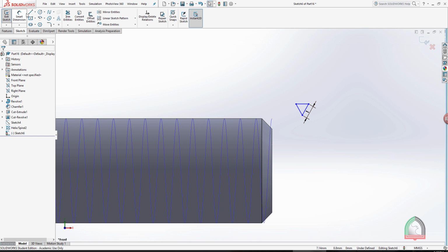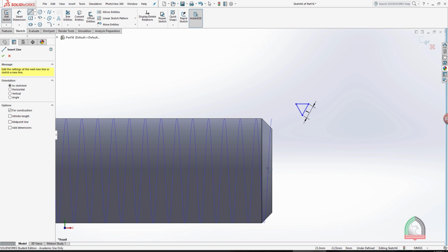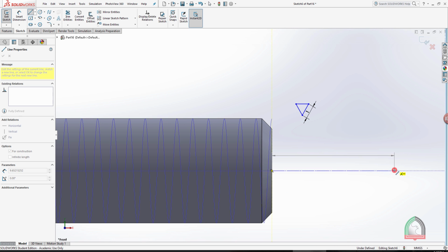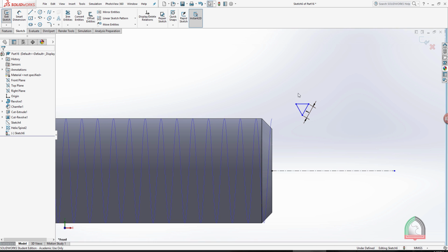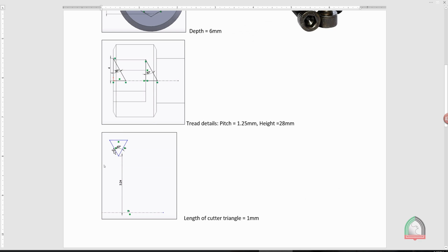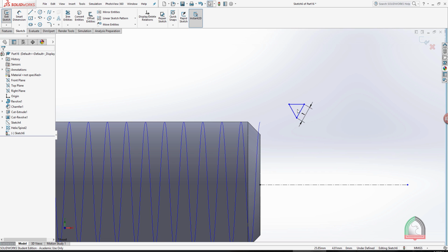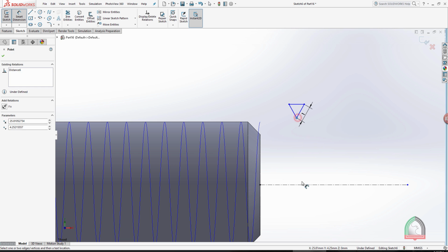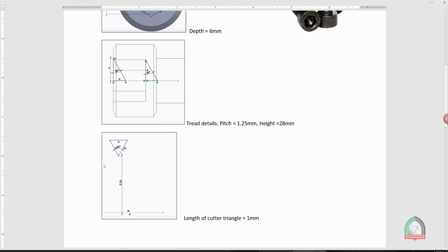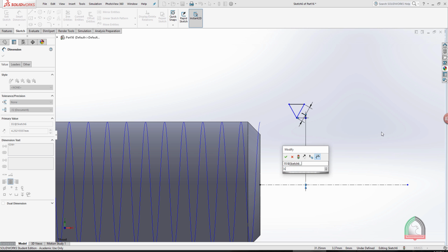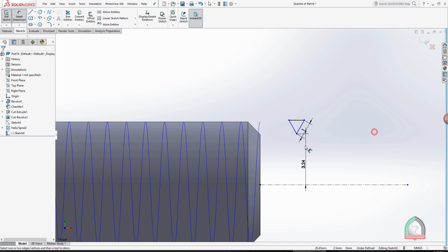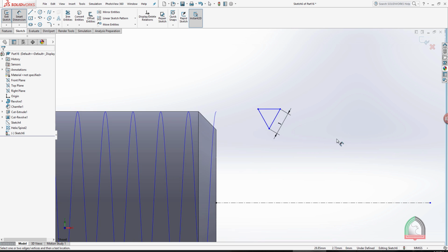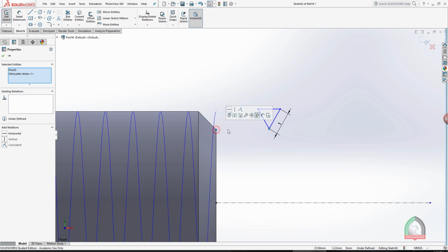Okay, now the center line. When we are selecting all the faces equal, then again there is no need to give the 60. Automatically the angle of the equilateral triangle will be 60, and we can maintain the distance from here to here. It's given already, 3.24. Okay, now we can make this point and this one coincident. So it is coming to the start point.